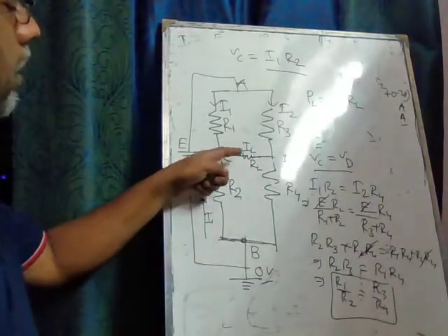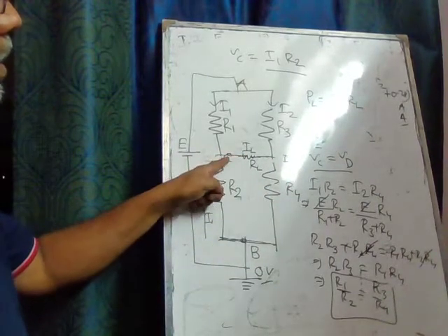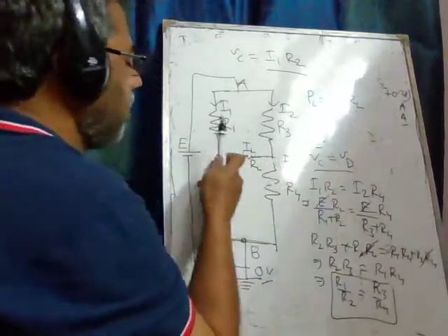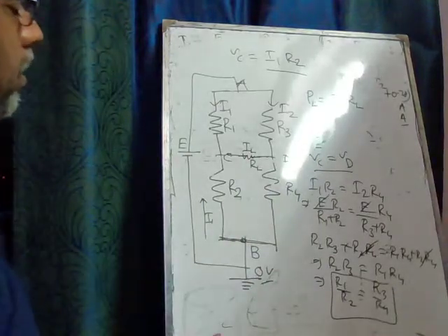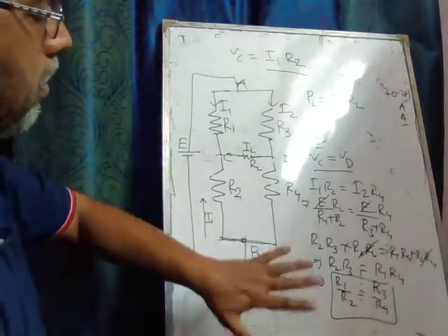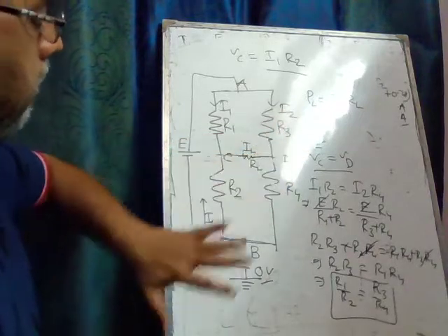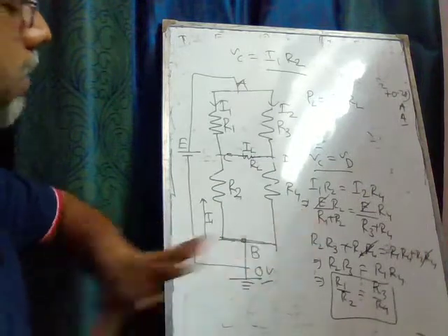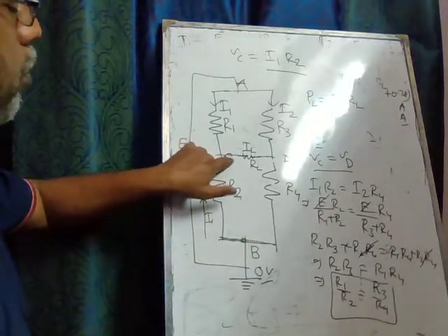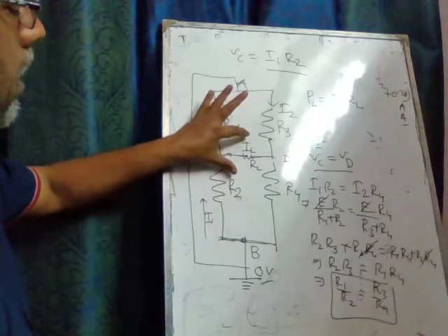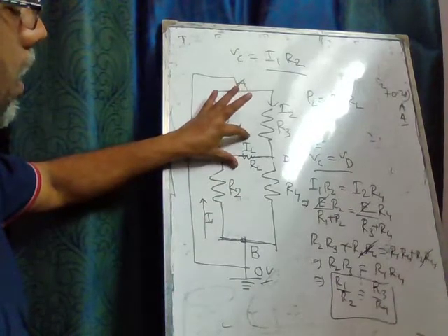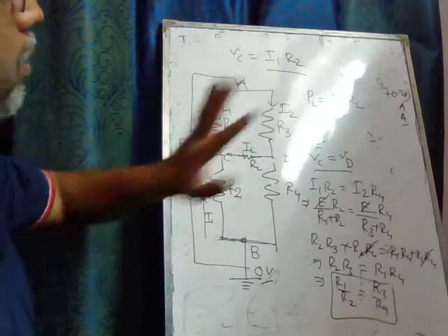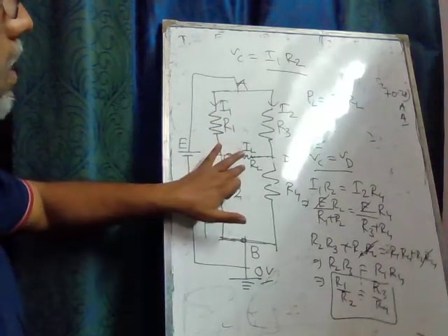If we know the current in the branch CD, and VC minus VD, we already know VC and VD. So from the difference of the potentials as we have derived, we can calculate the current I3 or IL, and IL squared multiplied by RL will give you the total power loss in this branch.